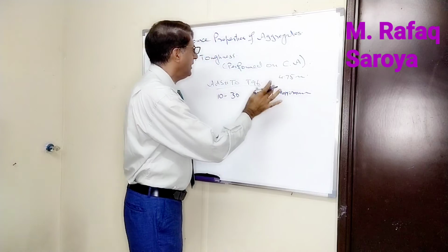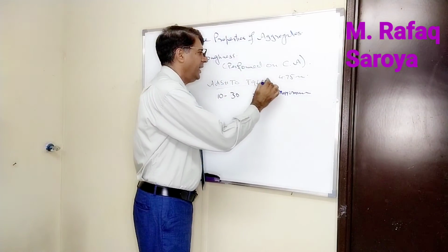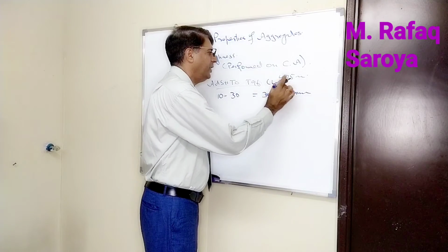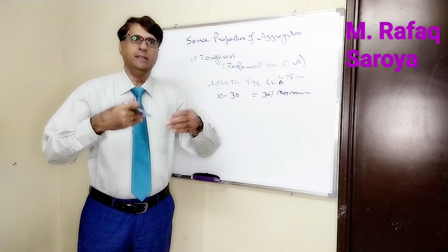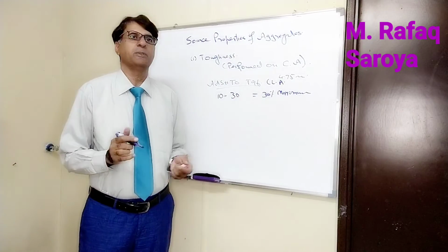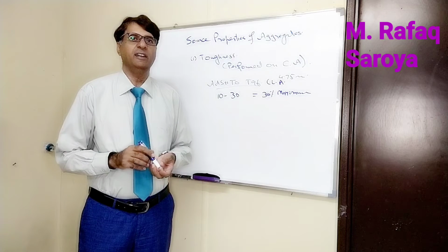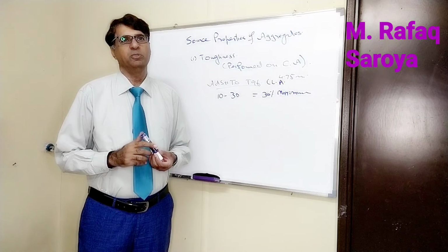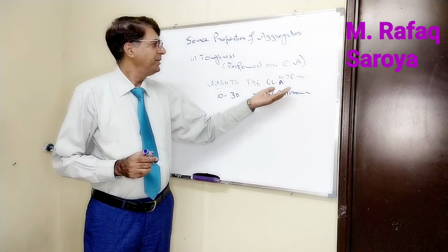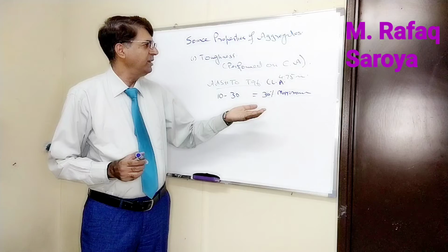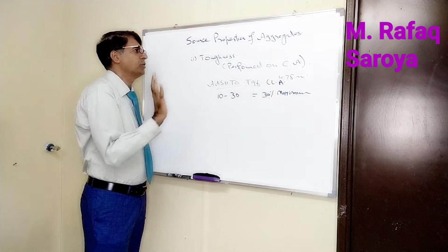It means if Los Angeles abrasion is performed over this one, the aggregate allowed to disintegrate due to this cyclic repetition is 30%. If more than 30% of aggregates are being degraded, it means that you will have to change your source of the aggregate. So this is the first property which I have already explained to you. I am not going to go in detail, and it is always performed on the coarse aggregate.